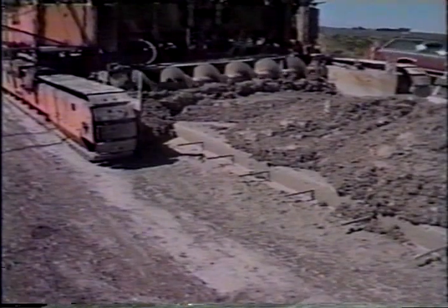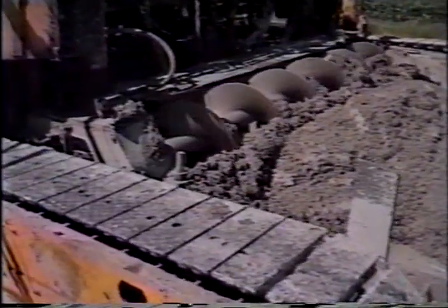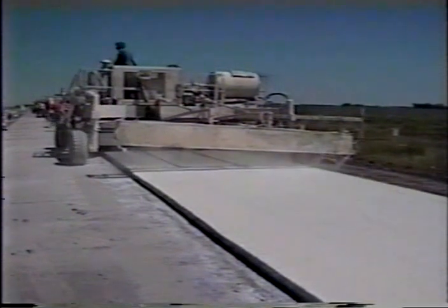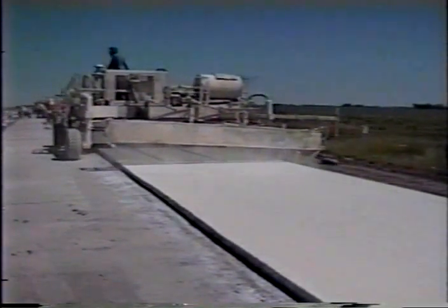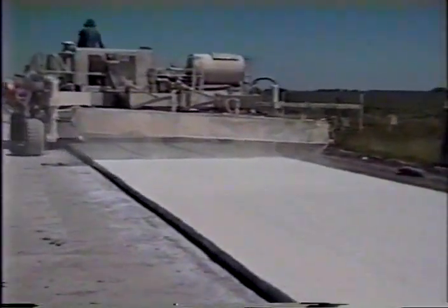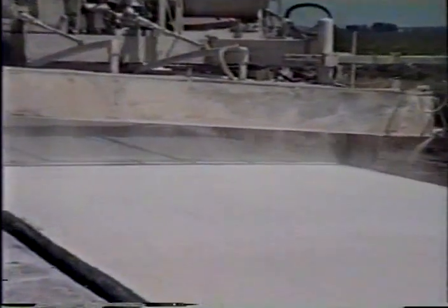Concrete placement is substantially the same for bonded concrete overlays as it is for new construction. However, trucks that must be operated on the clean surface should be fitted with diapers to catch any dripping oil or grease. As with any concrete, curing is critical. In normal weather conditions, good results have been obtained with a curing compound applied at 1.5 to 2 times the normal rate. Under extremely hot, dry, and windy conditions, more effective curing measures are required. These include wet burlap, polyethylene sheeting, and surface fogging.